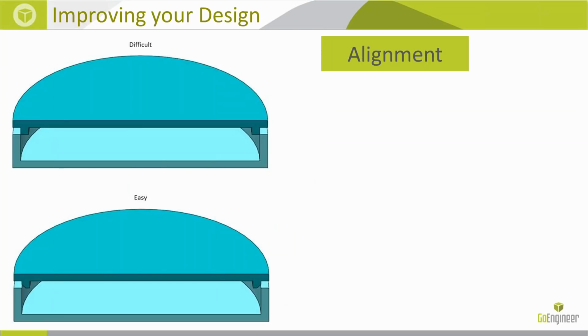So injection molded parts often have alignment issues. And in this example on the left, you've got a lid and a box. And you can design for perfect circumstance. But if you put a chamfer or a fillet for a good lead in, it'll actually help you make that closure for the lid to the box. There are alignment issues often with plastic parts. So, Arvind, can you tell us a little bit more about why we might see alignment issues?